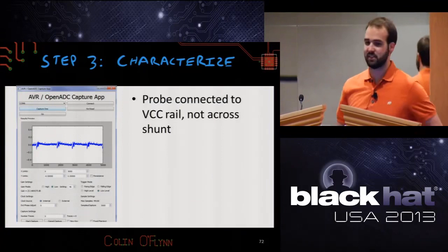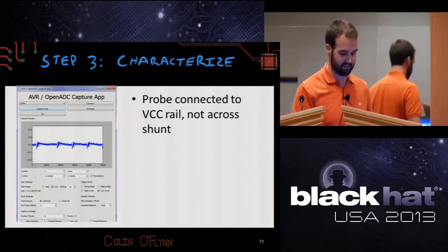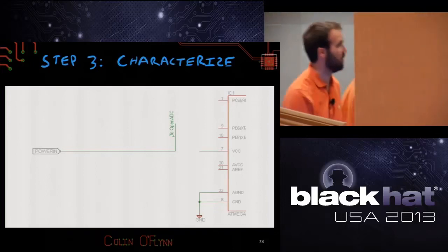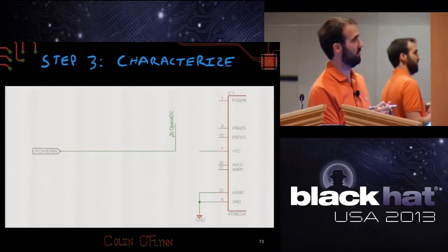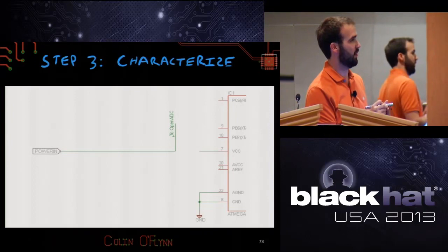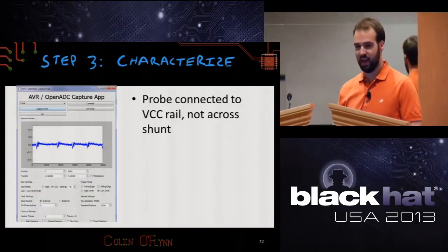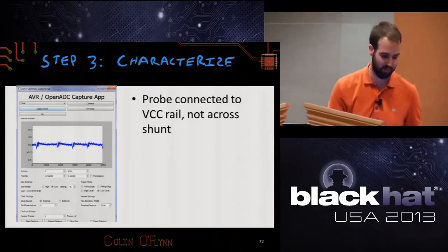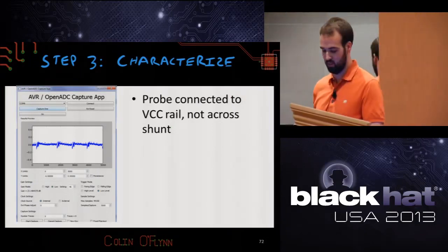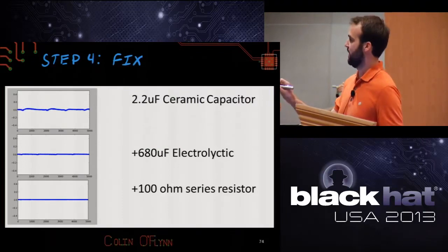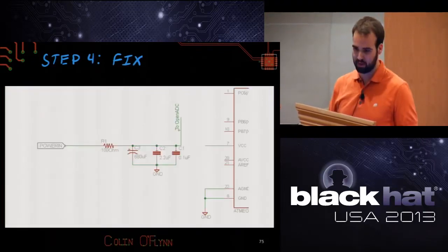If you have too noisy of a system, you'll need to take steps to mitigate that. So here what I've done is I actually connect this probe just to the power supply of the system. So the positive rail basically, and I'm then going to see how much noise is on that positive rail. If there's too much, it won't work very well. If there is too much, like there was in that previous case, I'll add filtering components to bring it down.